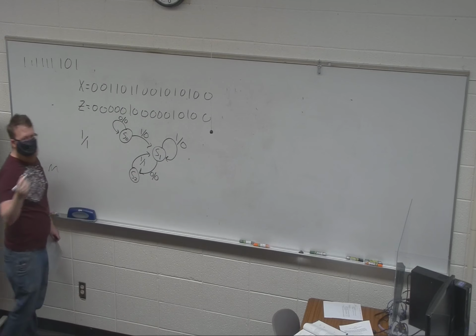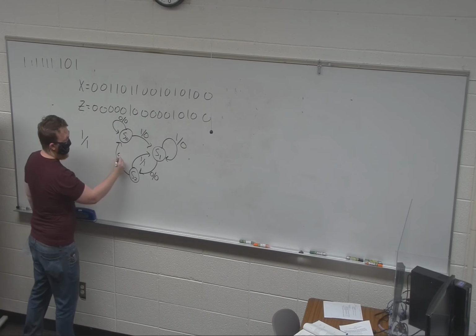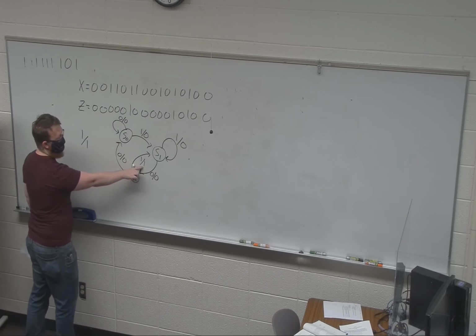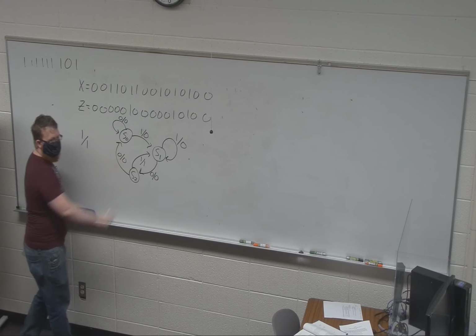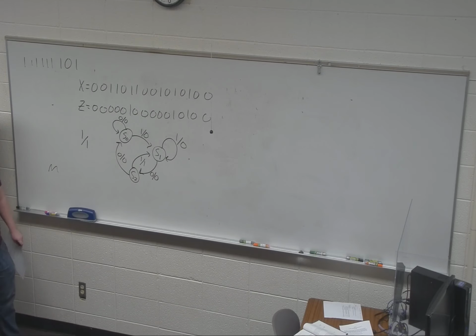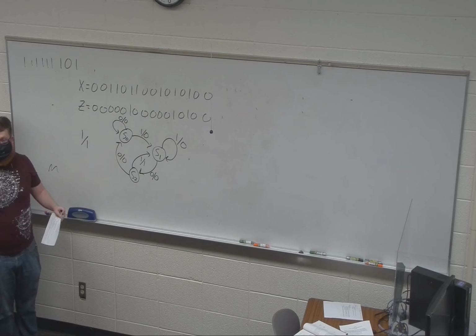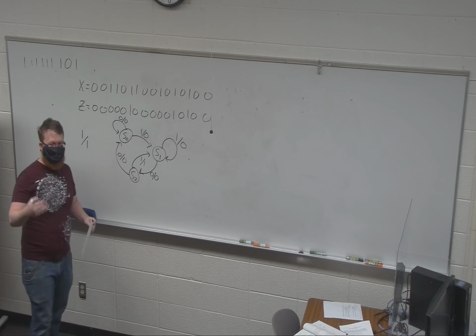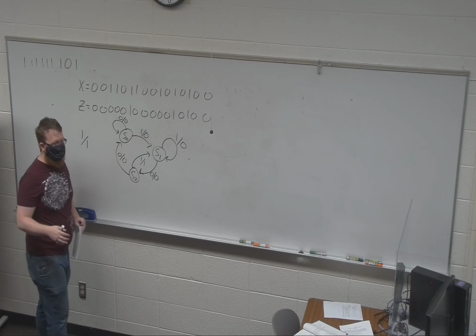And then if it sees a 0, it's not helpful. So notice here is our 1 output. When we do the state change, we get a 1. So that's Mealy. Moore, we know, has to have more states. And that's because the state determines the output.